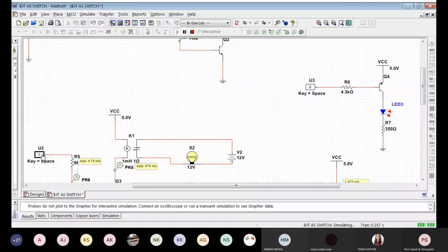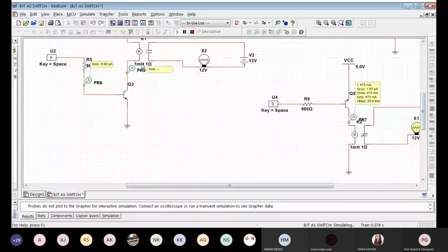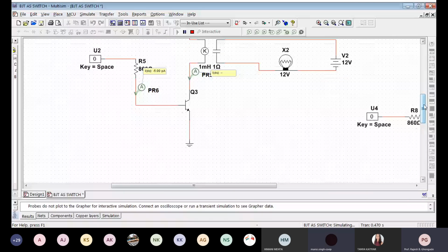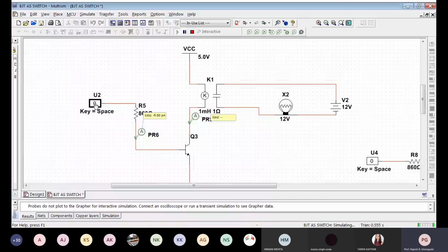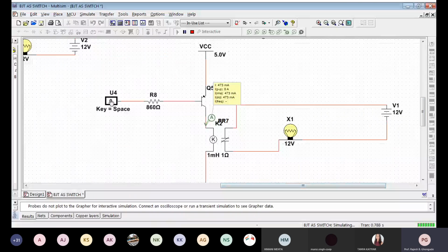See what is happening? Do you see what is happening, guys? Yes, sir. So if I want to switch on the relay, the lamp will glow because the circuit gets completed. Conversely, in case of NPN device, if this is 0, the relay is switched on, and when I assert the signal, that is make it 1, then the relay is switched off. You can see here the symbol getting changed like this. Okay, is that fine?